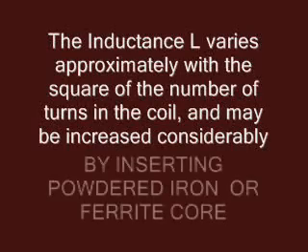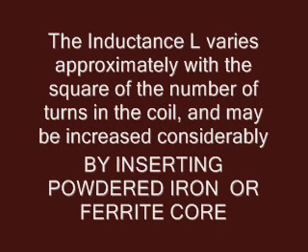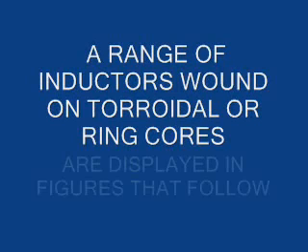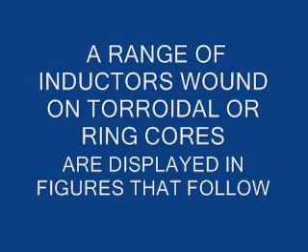The inductance L varies approximately with the square of the number of turns in the coil and may be increased considerably by inserting a powdered iron or ferrite core. A range of inductors wound on toroidal or ring cores are displayed in the figures that follow.